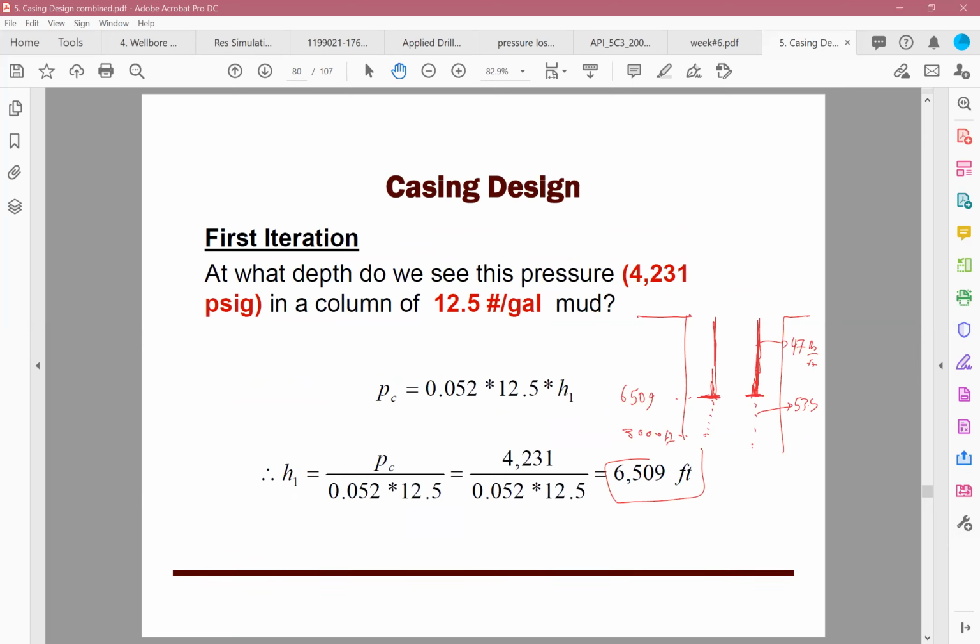You guys know it. You did the homework for axial tension. How do you calculate the axial tension at this point? Is it the weight of the pipe minus whatever the buoyancy force would be?